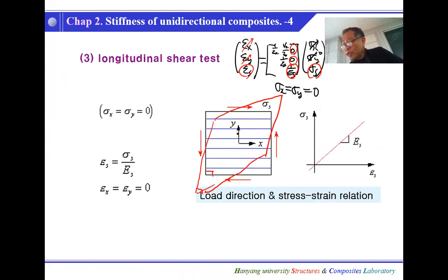So what you need to do is use 45-degree rosette strain gauges, where strain gauges only measure the extension length. So use the strain at 45 degrees, or these days we often use DIC, digital image correlation, which means that we spray and make a lot of dots, and then using the camera, we trace each point and how it changes the strain.